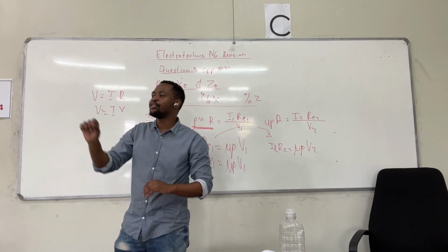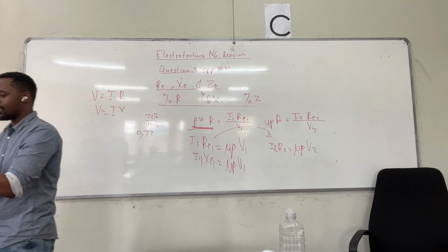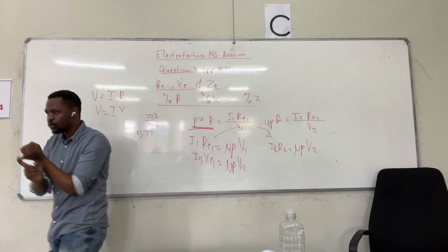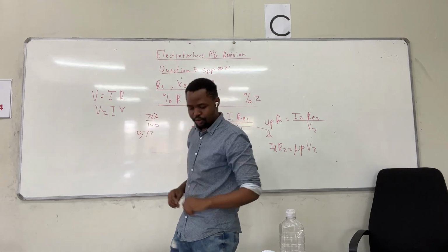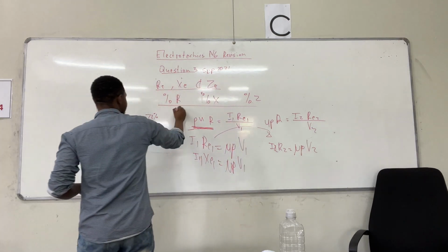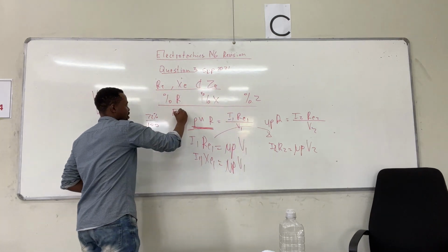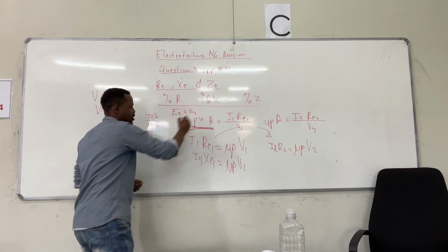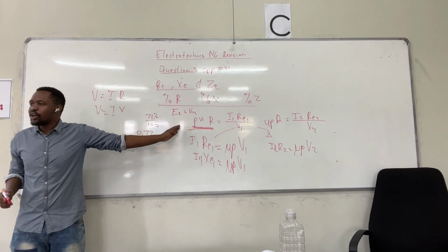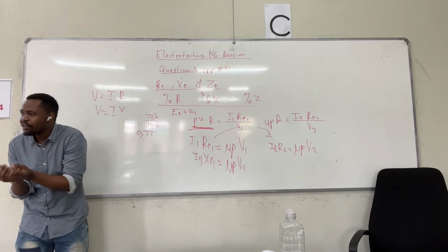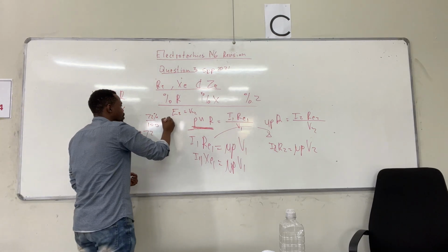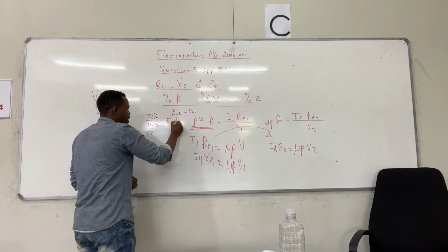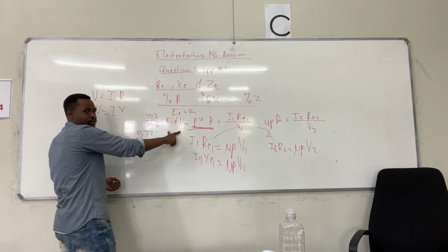It talks about the rise and fall of the secondary voltage. If you notice, when we look at a transformer at no load versus a transformer at load, you saw that a transformer at no load had E2 equal to V2. But once we connected a load, we started to have internal voltage drop, so E2 was no longer equal to V2.